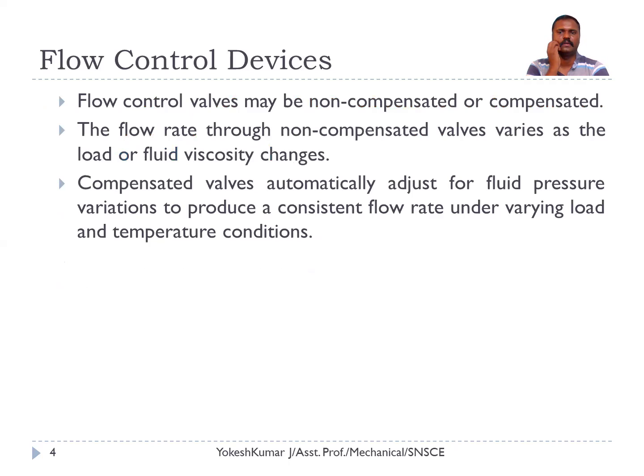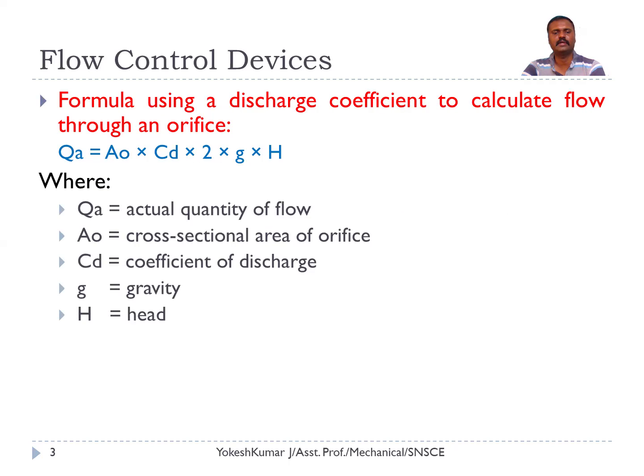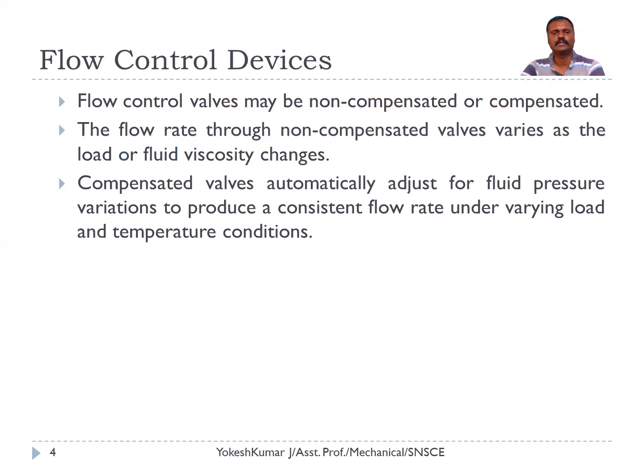So, if you want to control the flow rate, we have to control either pressure head or area of opening. So that can be accomplished with the help of pressure control valves. So normally the pressure control valves are pressure compensated or non-compensated pressure control valves.